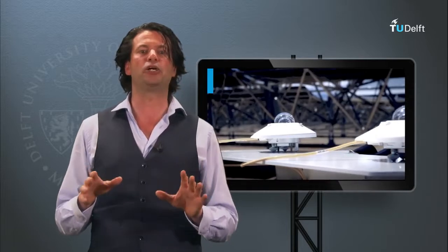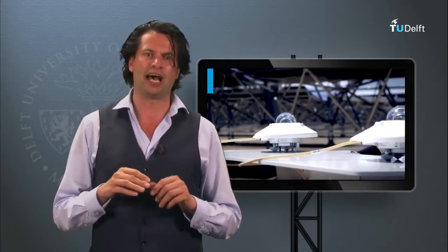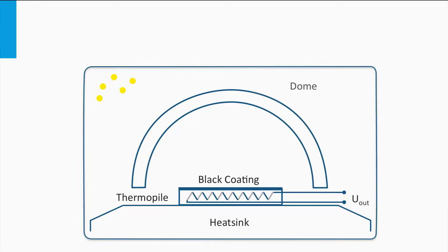For that, we use a pyranometer, and you often see these tools installed next to a PV system. These are instruments used to measure the heating power of radiation. A pyranometer has a field of view equal to the complete hemisphere and is sensitive to the full spectrum of solar radiation in the range from 300 nanometers to 3000 nanometers, and has a flat spectral response in the whole range. It allows us to measure the radiation very precisely, independent of the wavelength of light. It measures the thermal effect of the radiation.